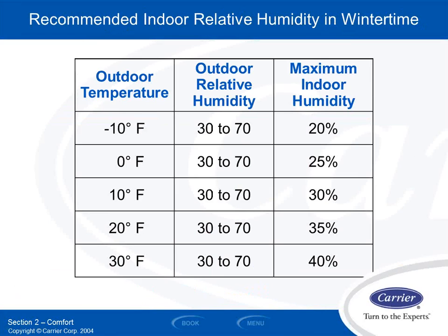Sometimes when we do add humidity to spaces in the winter, if we add a lot of humidity, we can cause condensation on windows. Remember before when I said the single pane window on a minus 10 degree day has an inside surface temp of 10 degrees, and the double pane was like 46 or 47 degrees. Those surface temperatures, if they are too close to the dew point of the air, then I'm going to have condensation form on those surfaces, the windows, and that condensation is going to run down the windowsill and eventually cause